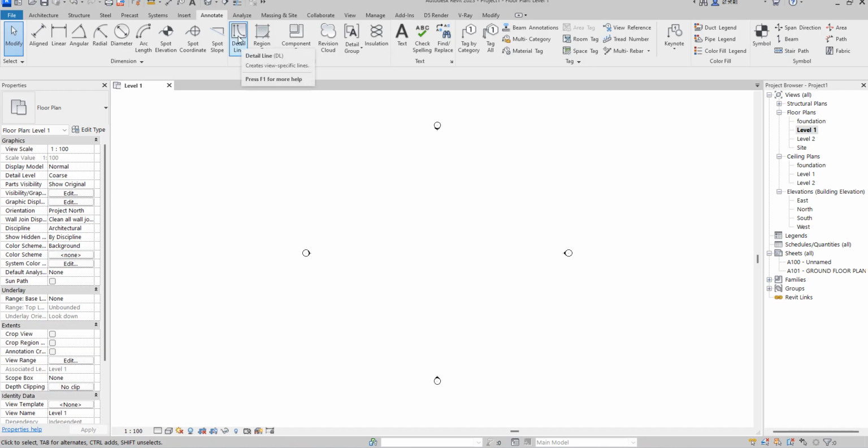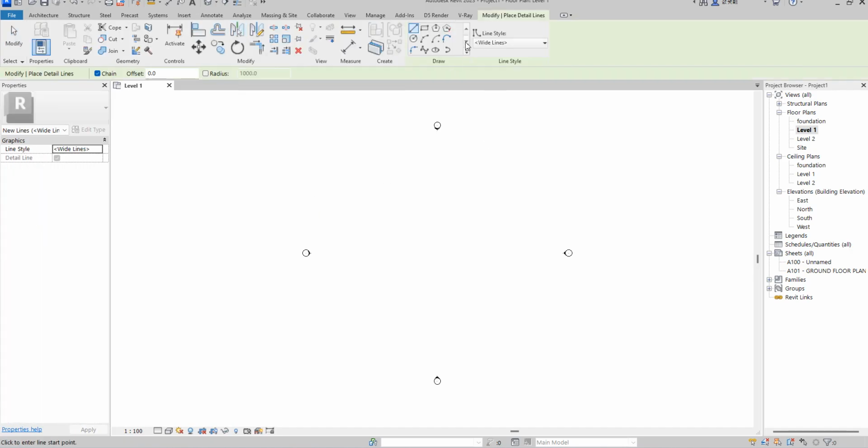This is what we do. I will select Detail Line. First I need to construct my circle so that we know the kind of radius I'm going to work with. So I'm getting my circle here and I'm working with a radius of 13,500. That is what I want. The total capacity of this hostel that I want is between 120 rooms and 130 rooms.